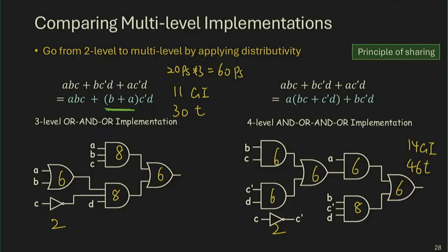When we did logic minimization, we were doing sharing. We let two minterms share the same implicant, or multiple minterms sharing the same implicant. It's actually the same idea over here. If you can let multiple implicants share the same hardware implementation, you can get some saving.